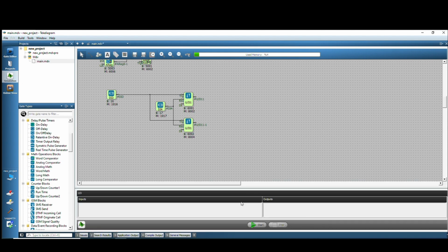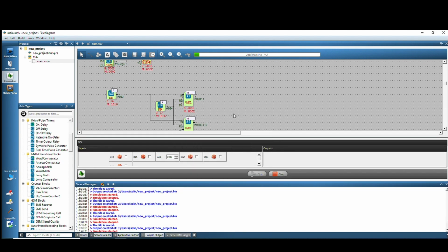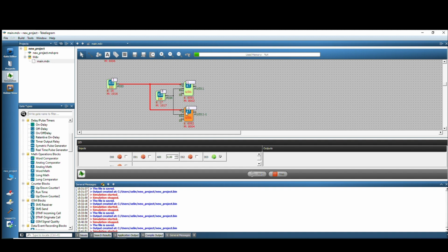Let's start the simulation. I'll get digital input 3 active. When I press it, the first trigger will be up, the other down by -1. It will start counting with each trigger received. One counts up, the other counts down. To reset the block, we will need to enter a value in digital input 4. When we activate digital input 4, a trigger came on the rising edge with reset inputs, and the blocks were reset.